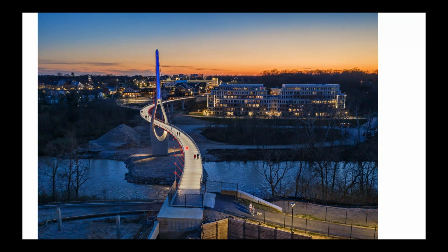The total depth of the bridge is 4'10". It's tracked off the deck thickness, and you've only got 3 or 4 feet of clear space to crawl through there. So it's not comfortable, but you can get in there periodically, inspect the dampers, maintain the dampers, and also inspect the weld and the quality of the inside of the bridge, the paint. So we did provide, I think, a total of 4 access openings along the length of the bridge.